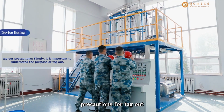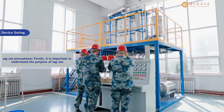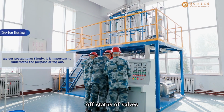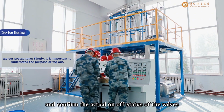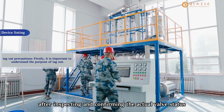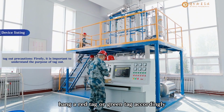Precautions for tag-out. First, understand the purpose of tag-out. The purpose of tag-out is not only to distinguish the on-off status of valves, but, more critically, to inspect and confirm the actual on-off status of the valves. After inspecting and confirming the actual valve status, hang a red tag or green tag accordingly.